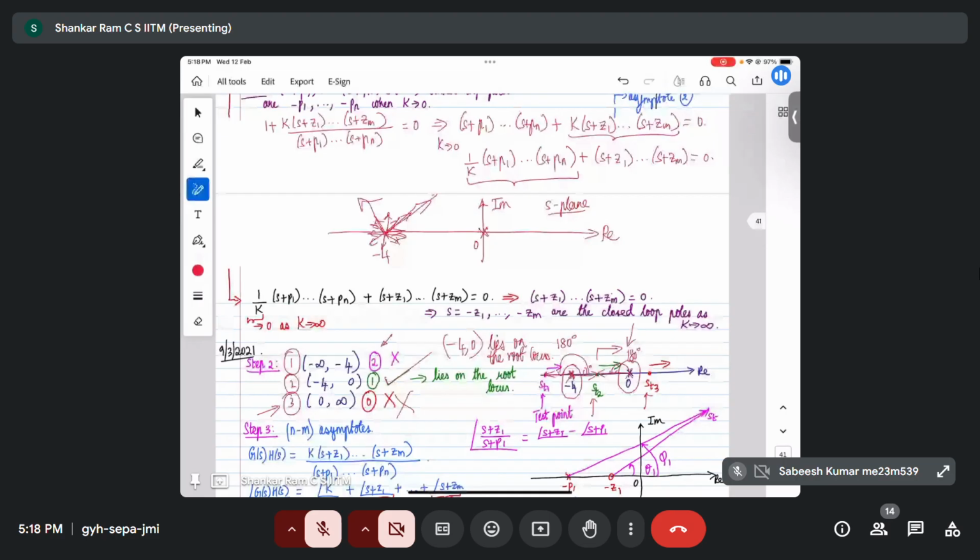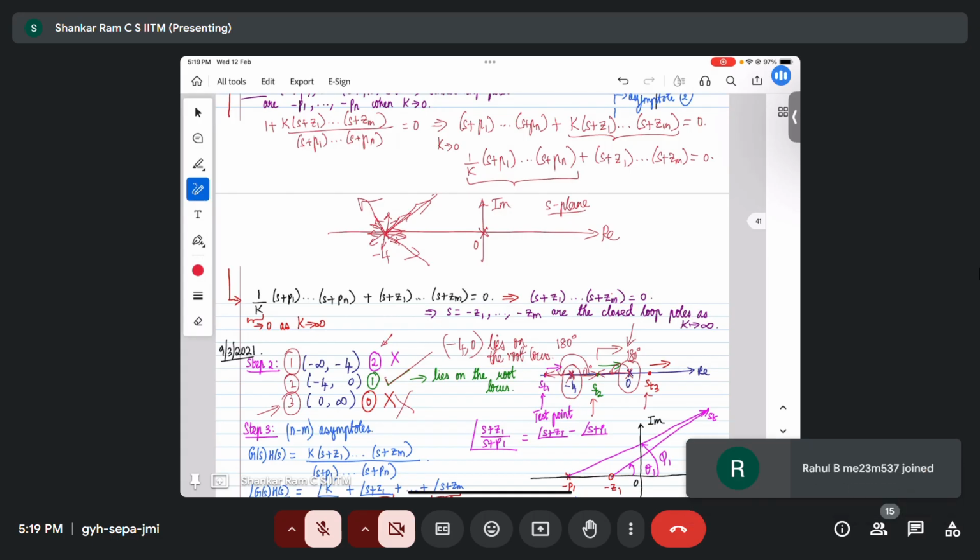So in the context of root locus, what is root locus? Root locus are the roots of the closed loop characteristic polynomial, which is a polynomial with real coefficients. The root locus branches talk about closed loop poles. So there is only one root locus branch starting from -4. Consequently, if the pole which starts from -4 is complex, there should be a mirror image which should also start from -4. Only then can we have complex conjugate roots, complex conjugate branches.